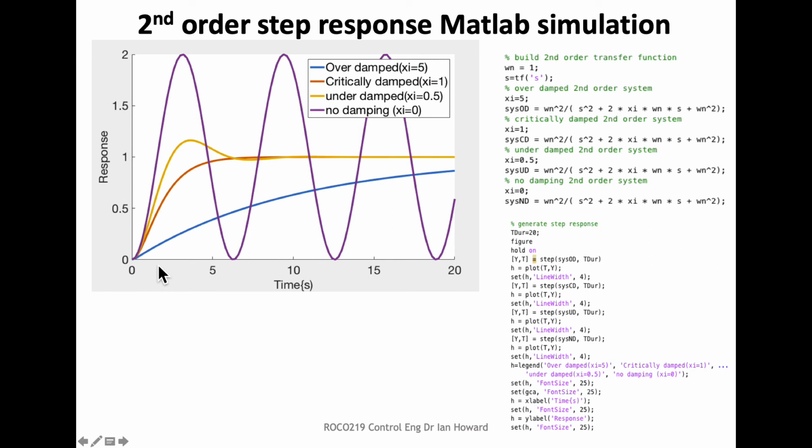Critical damping is when we go up as fast as we can without any imaginary part to the pole. So in other words, it's rising up as fast as it can without in any way being oscillatory. It's not going to overshoot. It goes up as fast as it can without anything being oscillatory, so there's no overshoot in that condition.